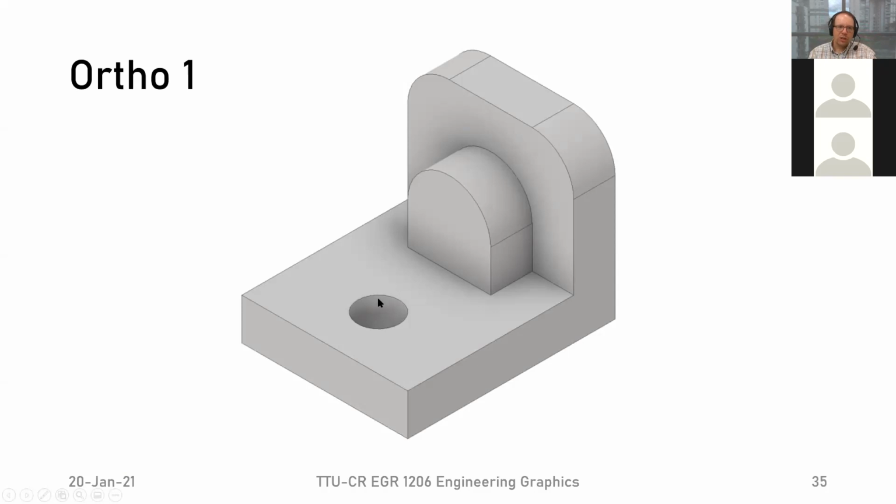You have a hole here, so you want to make sure that you do center lines. You have two different curves here, so you have to put center lines for those as well. You'll also have hidden lines for where this hole is, if you look from the right side. Those are the things, and I want you to do them nice and clean. Construction lines should be great.